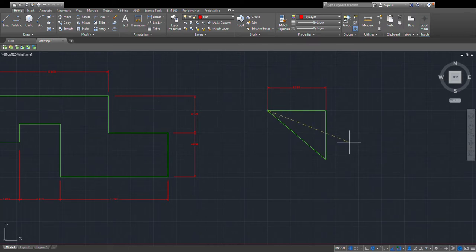Okay, again, the dashed arrow is the measure path. Notice that it wants to snap to the ordinate directions. If I do this, I'm not getting the length of the hypotenuse because these two dimensions are the same. So I want to actually measure the angled surface.